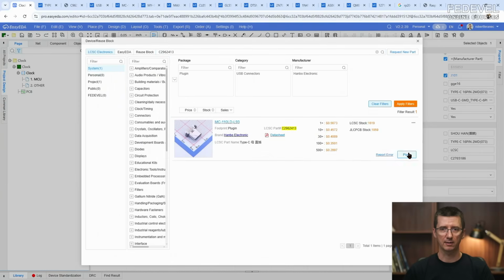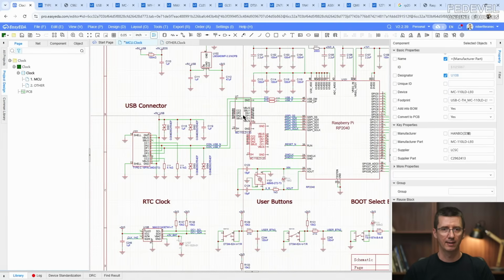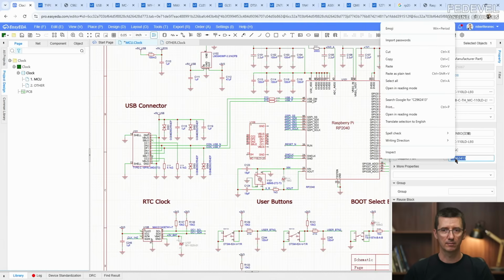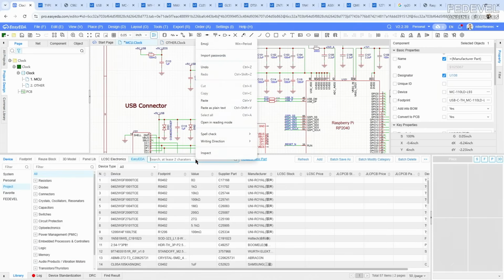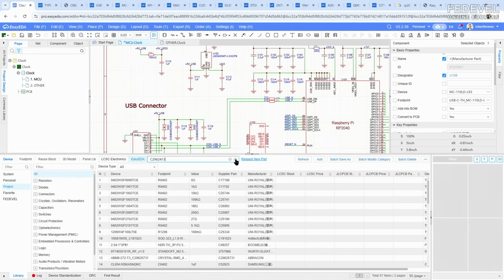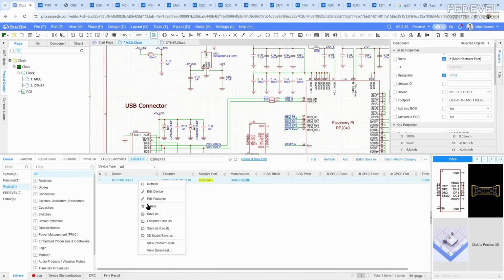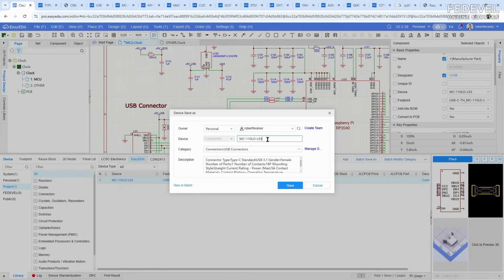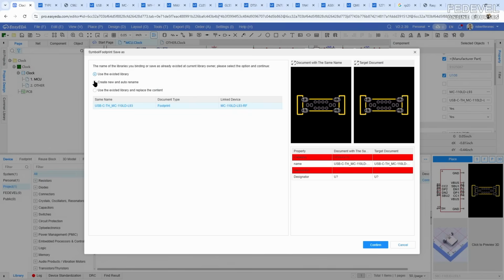And we can place it into our schematic. And this is going to be something new for you. We need to adjust the symbol, so I'm going to find the component here in libraries, and I'm going to create a new one from this one. I'm going to add RF here, and we are going to customize this component.